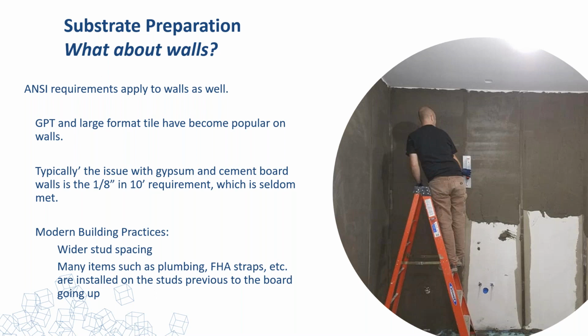If you need to float out a whole room, like this gentleman's doing, and this is our patching material, they prefer to do almost like a mud bed on all the walls. But this is bonded direct to gypsum. They're just screeding it off between their screed bars.